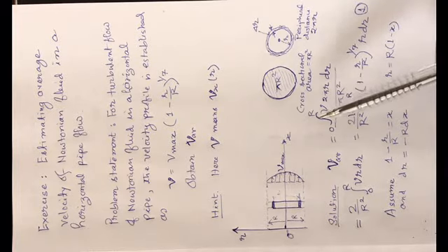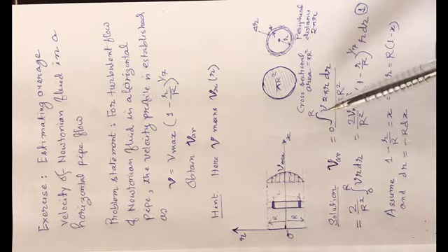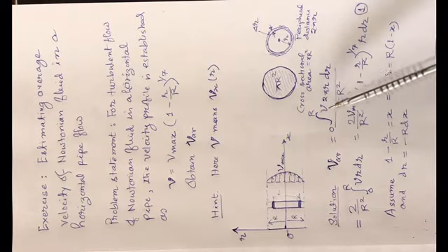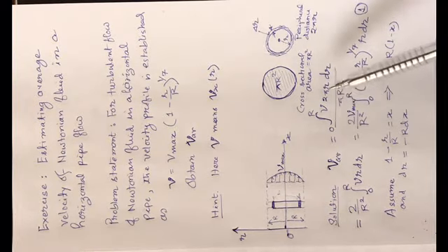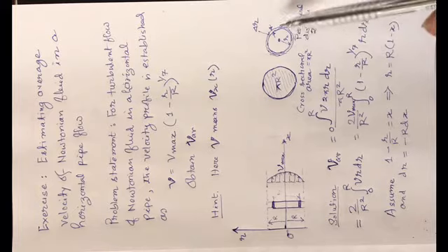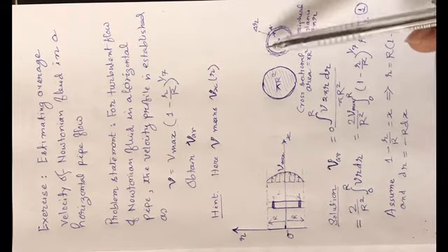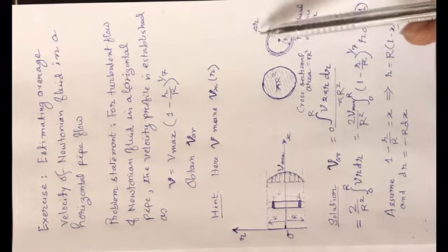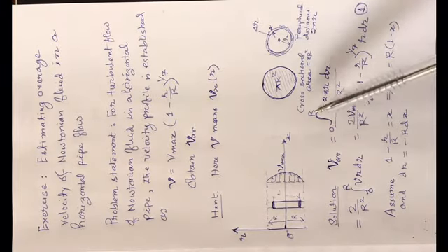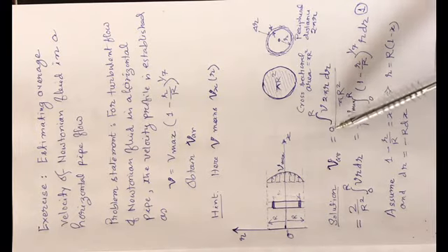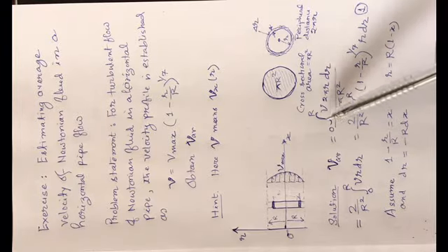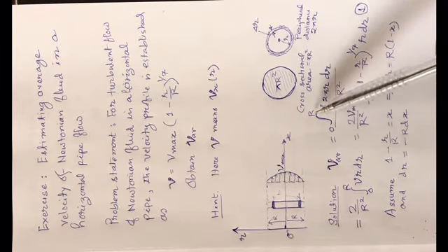So the net amount of fluid flowing through the tube is this velocity, Vx(r) in axial direction at location r, multiplied by the area of this ring. Since we are talking in differential form, we write it as dr, and to get the total value, we integrate from 0 to R, from the center up to the outermost location.